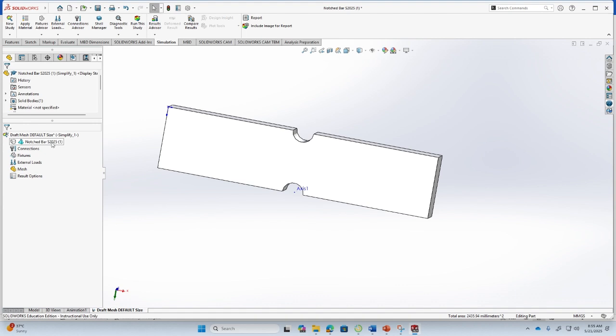Right, first step. Now, in any finite element analysis, essentially, you have to follow a 4-step approach, okay? The first step is to make the part, drawing of the part and any simplifications related to it. So we have already done that now, right? And basically bring that part in and create a study. So this part thing we have done.